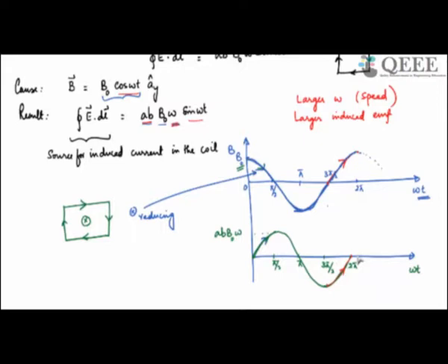So, the induced EMF is induced in such a way that it tries to oppose the change. The change here is reduction in field, and the induced EMF is trying to minimize the reduction. Here the change is increase in field in the negative direction, it goes maximum in this negative direction. The result is that my induced current produces a magnetic field which is opposing that change. So, this illustration tells us how Lenz's law is working. That is one learning from this example.